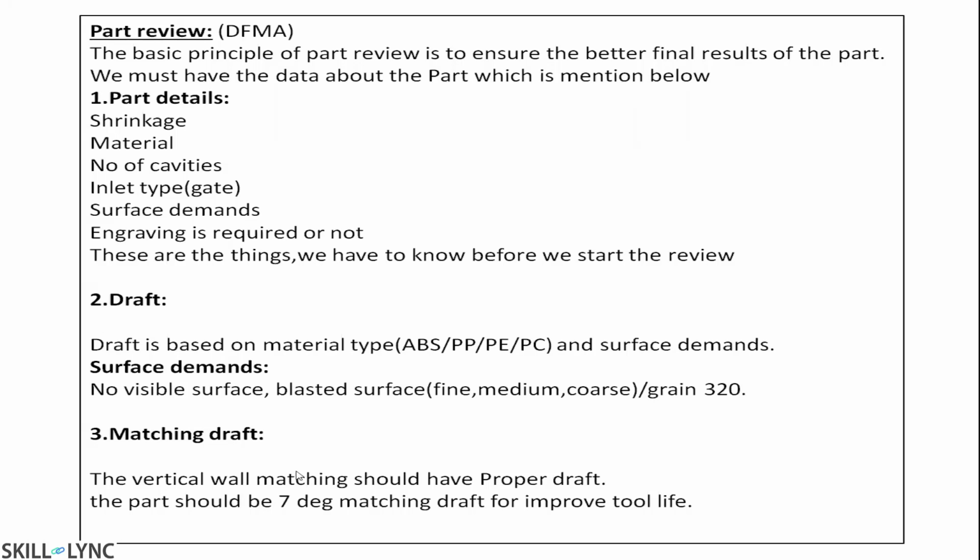And what is matching draft? Where the core and cavity are closing, there we need 5 to 7 degrees to avoid the rubbing between the metal to metal surfaces.